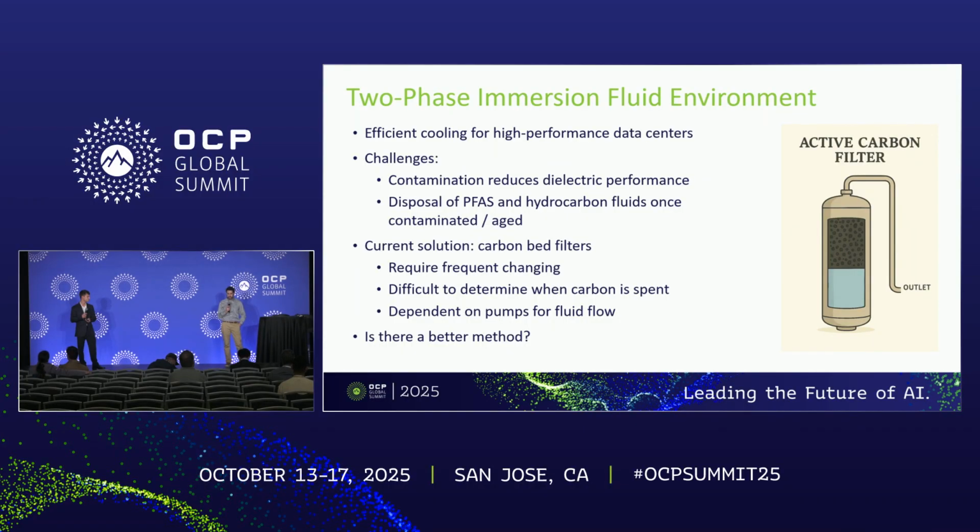And if your filter does happen to get overloaded, it could cause the breakthrough of contaminants back into the fluid. Also, depending on the contamination, it could require multiple filter changeovers, which could lead to an appreciable fluid loss over time. So it was with these limitations in mind that we asked the question if there was some other means of fluid purification that could assist in this current filter process.